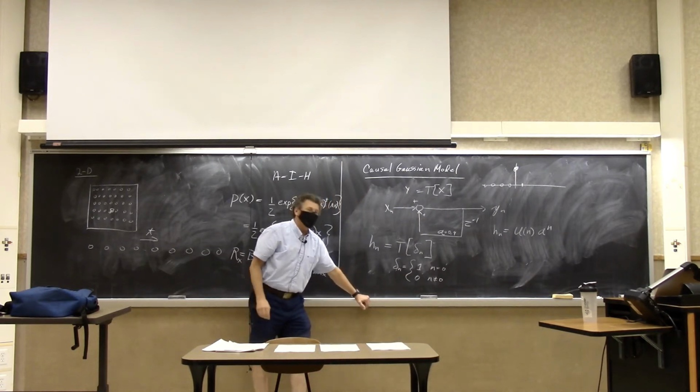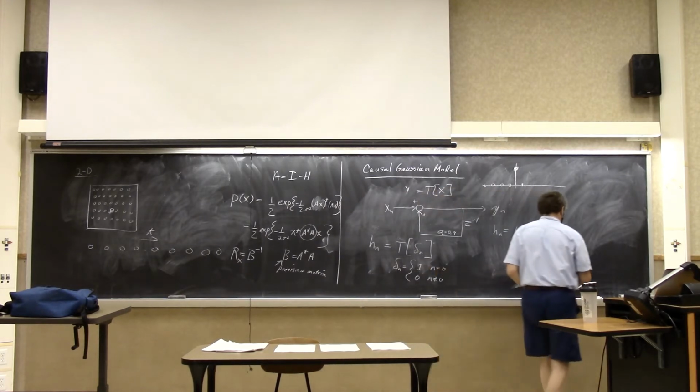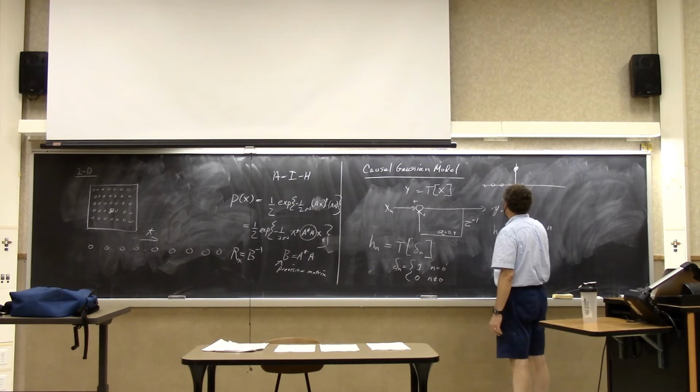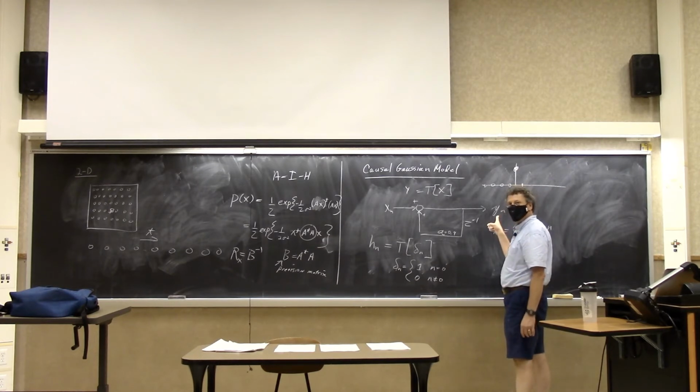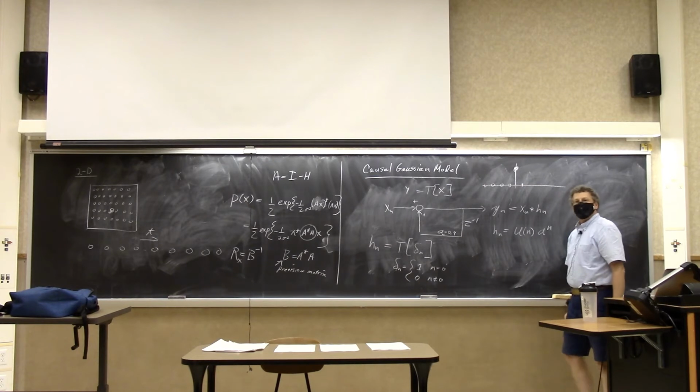Do you know what a Green's function is? That's also kind of an electrical engineering concept because it really comes from electromagnetics. Green's function is sort of a generalization of an impulse response for a space-varying system. But anyway, this is called impulse response. And the classic result is that for a linear time invariant system, you can calculate the output as the input convolved with the impulse response, okay?